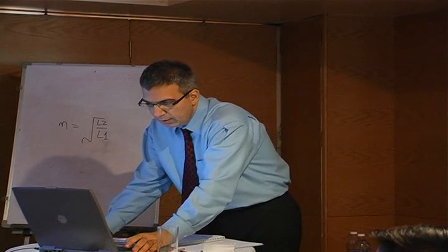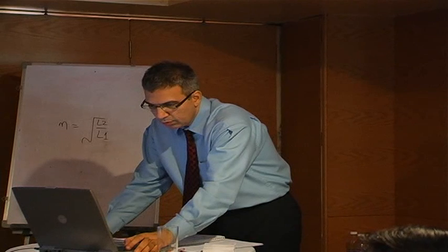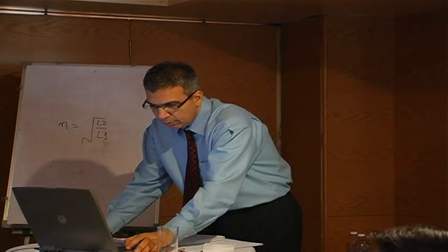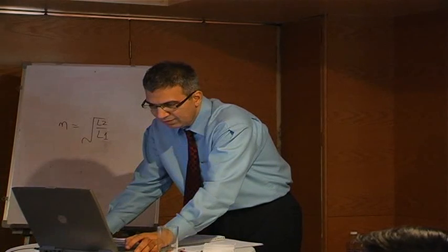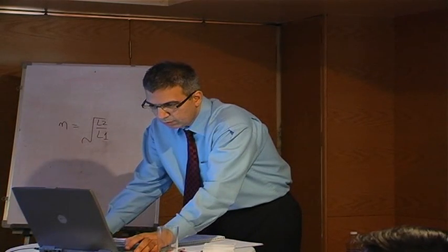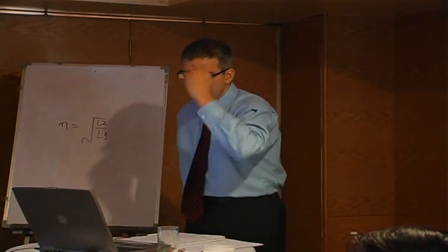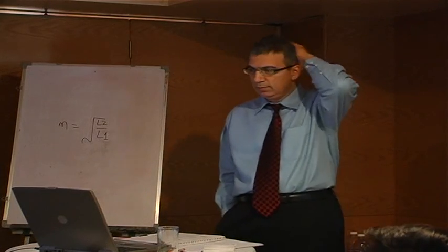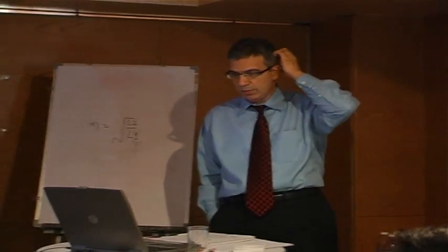Okay, and if you look at the output current, let's look at our D1 and D2 current. We plot it in a new window, D1 current, and then D2 current. Those are your D1 and D2 currents, which are overlapping simply because they have a 60% duty cycle compared to the 40% on the other side.